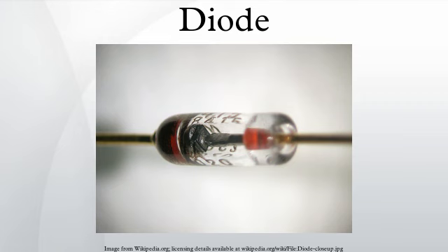If the depletion layer is large enough to catch the whole shower or to stop a heavy particle, a fairly accurate measurement of the particle's energy can be made, simply by measuring the charge conducted and without the complexity of a magnetic spectrometer, etc. These semiconductor radiation detectors need efficient and uniform charge collection and low leakage current. They are often cooled by liquid nitrogen. For longer-range particles, they need a very large depletion depth and large area. For short-range particles, they need any contact or undepleted semiconductor on at least one surface to be very thin.